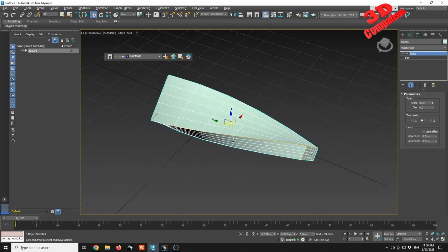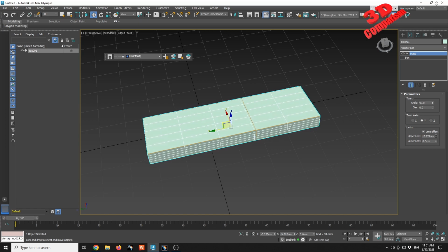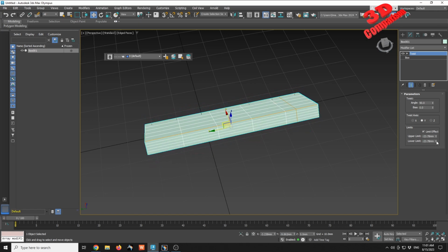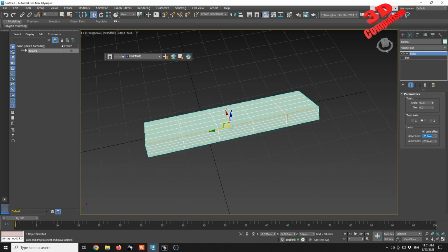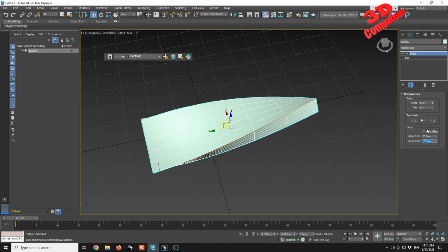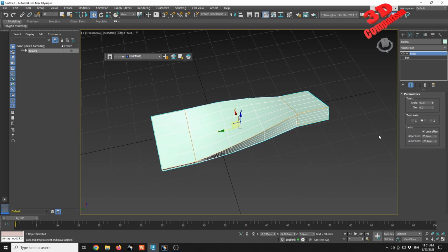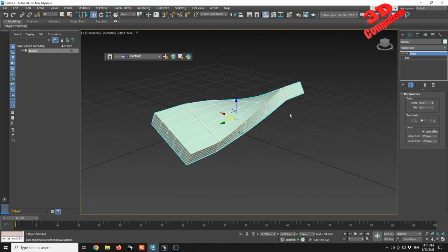And we can also influence the limit if we don't want some areas to be influenced by that. As we can see, this is the upper limit. So the upper limit in this case should be with a negative value, and the other one should be with a positive. So if I'm adjusting one, both will be adjusted. So I will just clear that like this. So have that limit, and now have the limit enabled. So you see now the software allows me to have one positive and one negative. And now I can just slightly increase the angle of rotation.